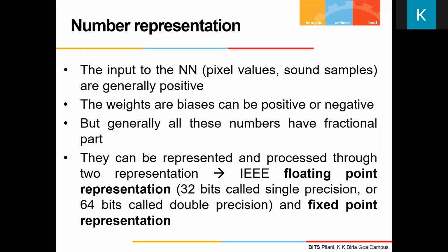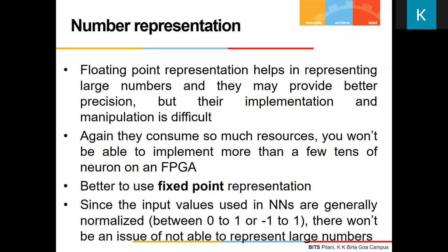In hardware, actually, I have two choices. I can either go with the floating point itself, which may give more accuracy, or I have the choice of using fixed point representation. Now, the advantages and disadvantages you might already know. Using floating point, you can represent very, very large numbers. That is one advantage. But again, its hardware implementation is quite challenging.